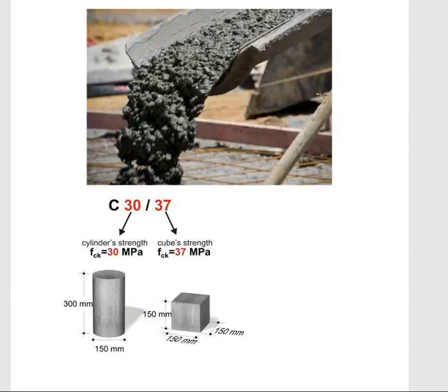Today we will talk about concrete strength. What is concrete strength? Concrete strength means how much load concrete can carry before it crushes. In construction, we mainly talk about the compressive strength because concrete is very strong in compression, very low in tension. So, if a concrete cube or cylinder is pressed in a testing machine, the strength tells us the maximum pressure it can take.